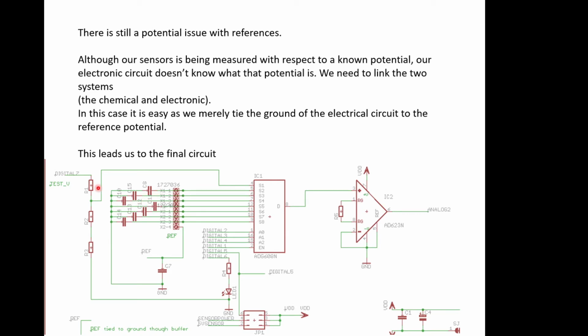And then the interesting thing is here we've got a resistor string, which is basically just a potential divider, and this allowed us to present a known voltage to this input here, which we could then switch through here, which allowed us to test whether or not the multiplexer and the amplifier were working correctly remotely. Because if we can read the right voltage when we switch to this point, we've got some built-in test, and then we know that everything's working okay. And if the signals coming into these other ones are a bit dodgy, that means the sensors are broken, not that the electronics are broken.